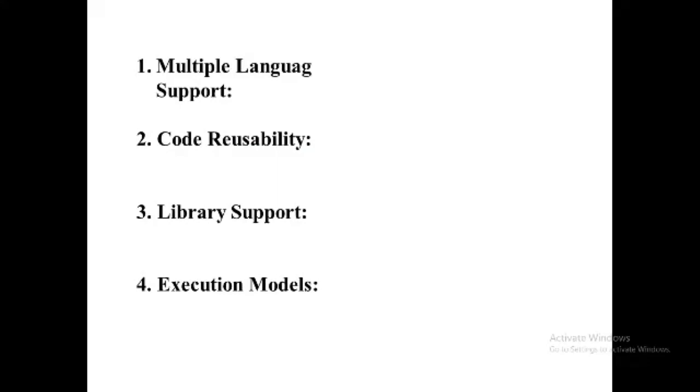Other additional options are also available for IEC 61131-3 programming languages such as ST, called SIMATIC S7-SCL, or SFC, called SIMATIC S7-Graph, which provides an efficient way to describe the sequential control system graphically.